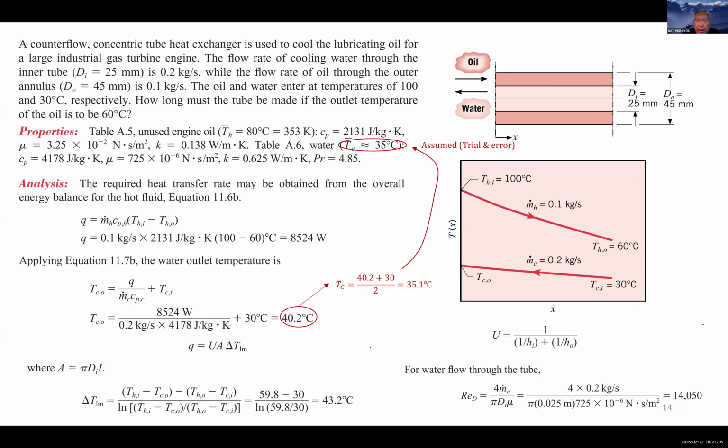So rearrange this equation. You can write UM as a function of m dot and DI and substitute this into the Reynolds number. Then m dot is specified, DI is specified, mu you already found.